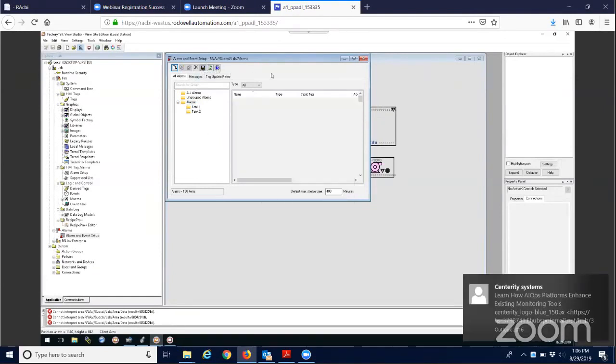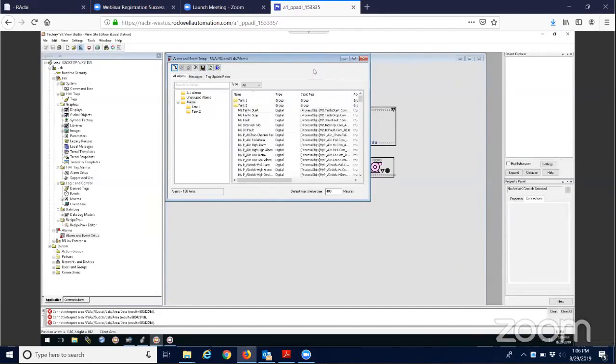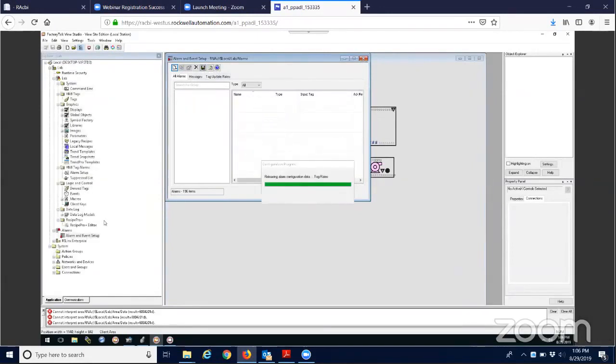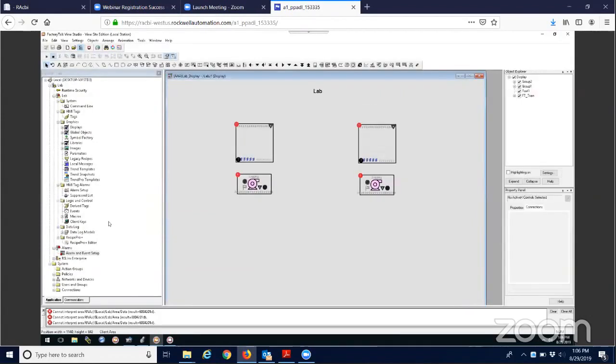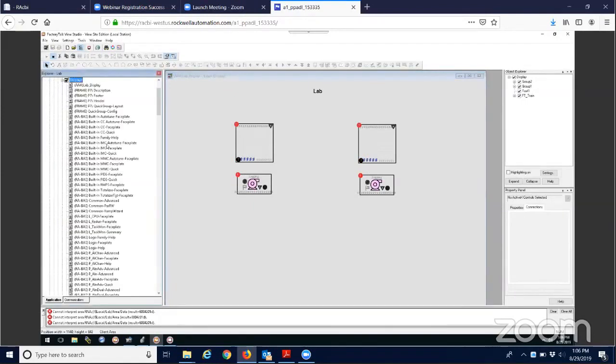Save it. If anybody hadn't seen that before, that's a newer feature inside of FactoryTalk View. Before, we had to just go into the alarm class and write in what our filter was, and you'd have to manually use that drop down. You can now set up little folders and set everything up. So instead of just the alarm class filter, you put them into their own little bucket.